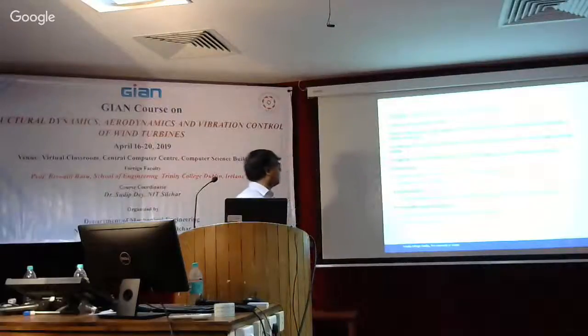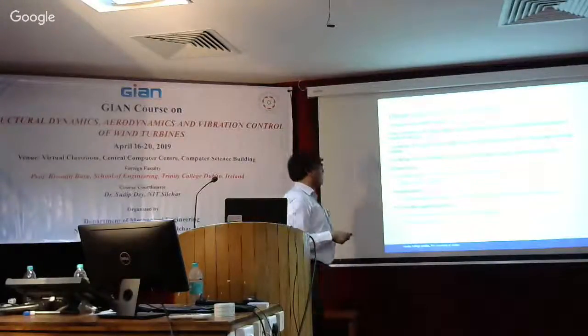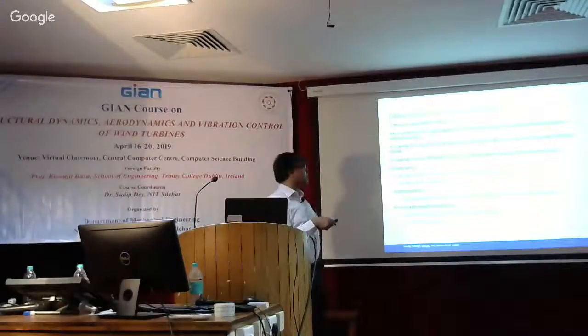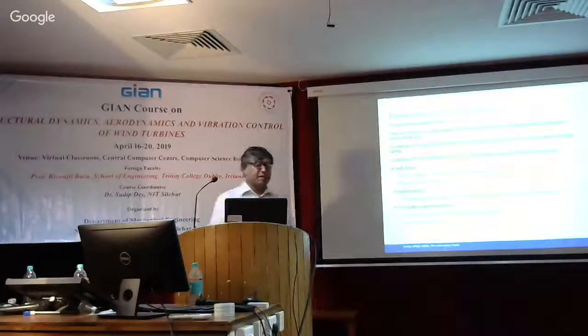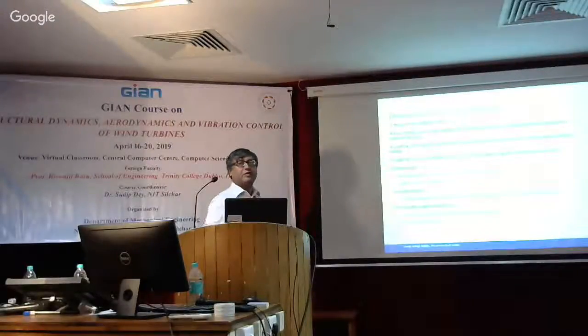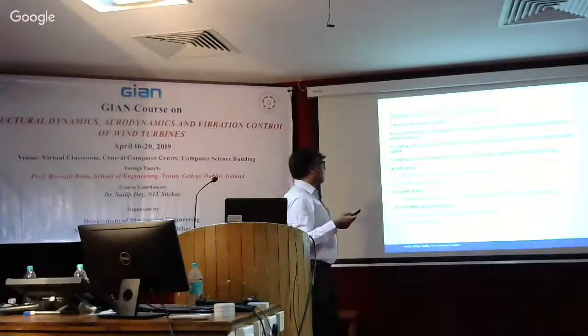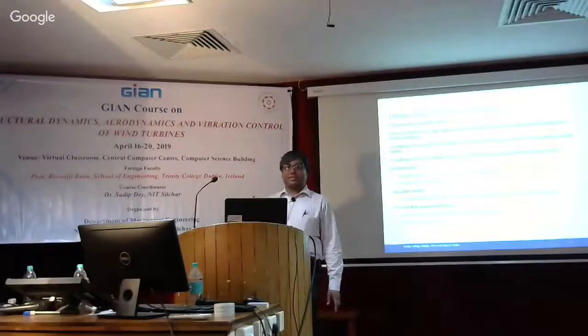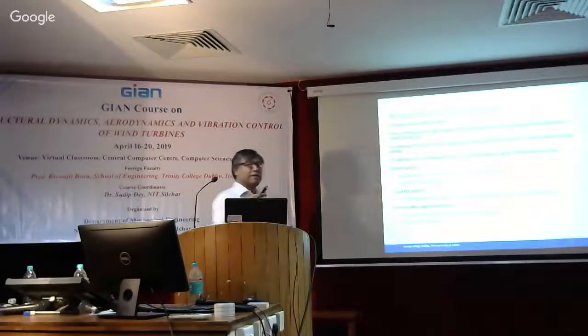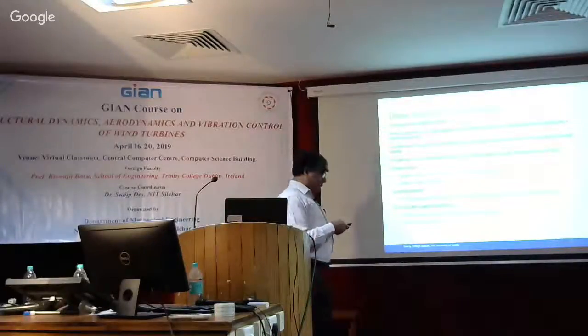Drivetrain torsional model, like the blade model, you can have drivetrain torsional model, and fixed speed model, and variable speed model. And we have actually a paper where we coupled the blade model with the drivetrain model, and it's a paper published in Engineering Structures with a former student of mine, and Steiner. It's another paper to look at because we did a lot of studies on what is the impact of a grid fault on torsional vibration of the drive. That coupling with the generator is also there. We took a different machine actually, WFN induction generator, and there's a paper in Wind Energy as well. So those are some of the papers to look at. I can give those references to you.